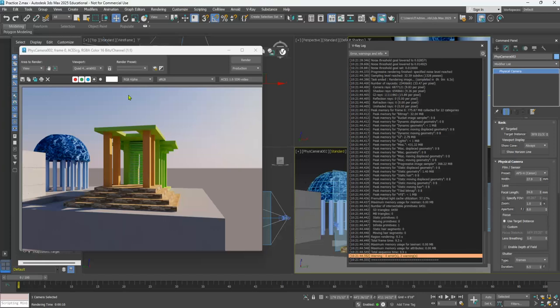So right now, when the light hits this blue dome, it's going to bring an extra amount of blue light to the space. If I painted the floor black, what's going to happen? We're going to lose lighting in the space. If I painted the floor white, we're probably going to get an overexposed image because now the light is stronger and there's more light bounce. As you apply more materials, you'll probably see it get darker because different materials absorb light differently. Right now we just have basic colors here. So keep that in mind, and see how your room changes depending on the material application you have.